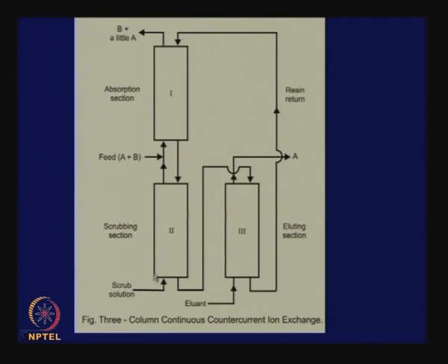The solution is coming, the feed is coming here, it goes to the absorption section, and it gives out B plus a little A, and the solution will go now to an elution section, where the eluant will regenerate the resin, it will go through, and it will also give A out here.